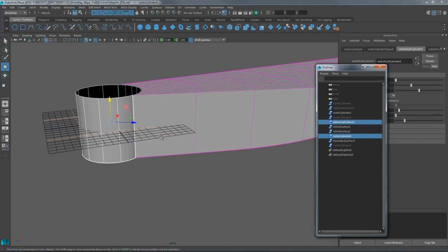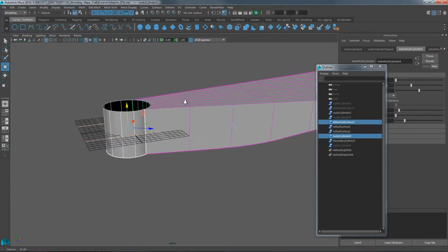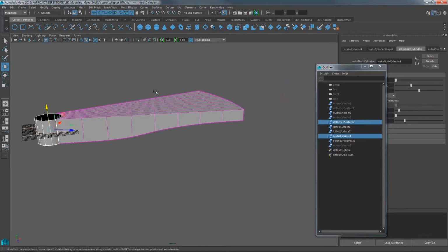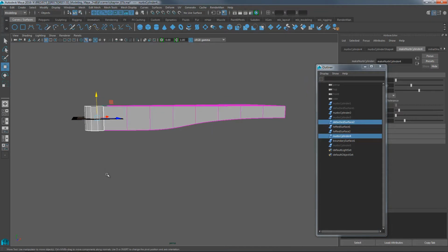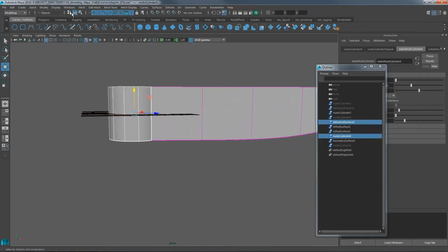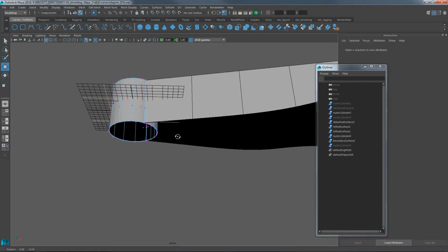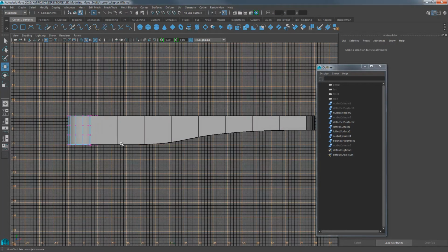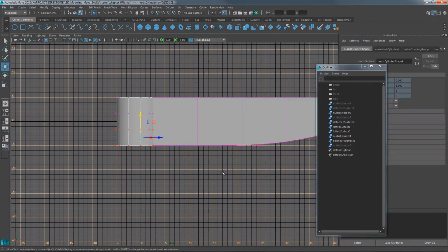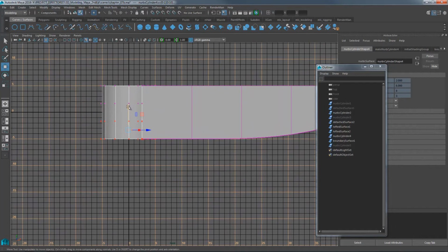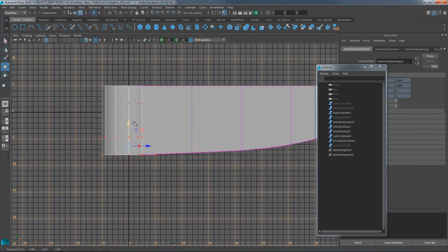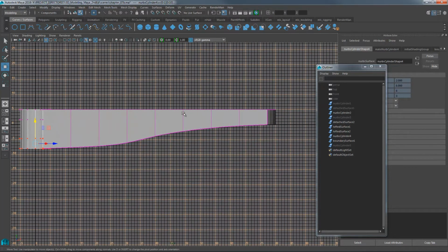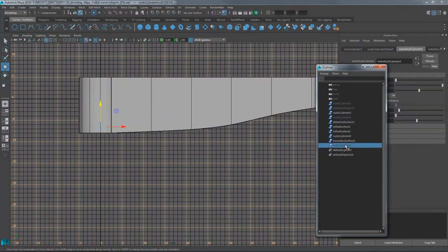And I've already done the hard work of measuring everything based on where it is right now. I don't really want to go up. Everything else would have to change. So I just want to go down. So I'm going to tag the CVs of these objects on the bottom side. So I'm selecting from the front view, tagging these CVs. I'm going to move it down. And I'm eyeballing at this point. I'm going to make a good guess because I'm looking for good proportions.